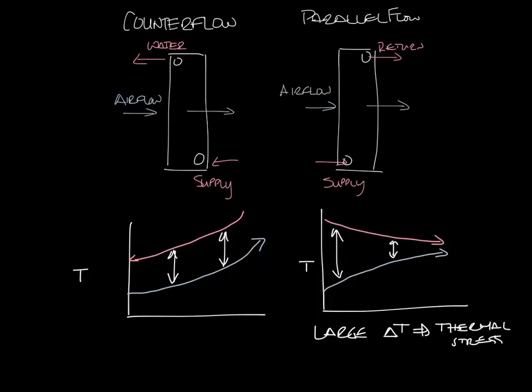Parallel flow coils are good if you're trying to bring the air and water temperatures to nearly the same temperature. But counterflow coils are typically more efficient at heat transfer than parallel flow coils are. So that's the difference between counterflow and